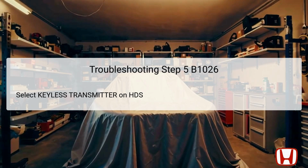The HDS will then allow access to the data list, which reveals the operational status of the door lock mechanism. This step is critical for diagnosing whether the keyless transmitter is effectively communicating with the MICU. Understanding the interaction between the keyless system and the door lock is essential to resolving the issue.